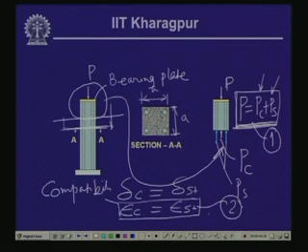As you can observe here, the restriction on the deformation is that the deformation of concrete and deformation of steel are the same, and based on that, this compatibility criterion has been arrived at.